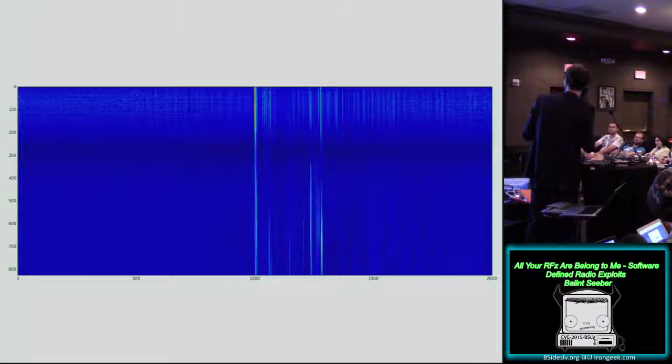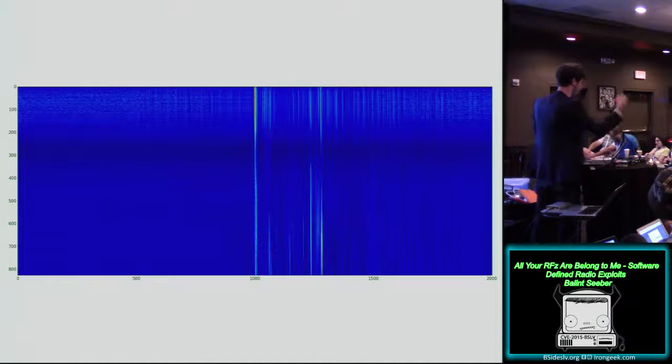And that's essentially the visualization of multipath, because you can see all the different signals coming in from the different path lengths that they have to travel through, propagate across, to get to your receiver. And so an equalizer is important because it essentially mitigates against all these signals that end up destructively interfering.